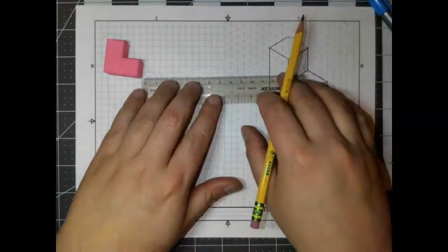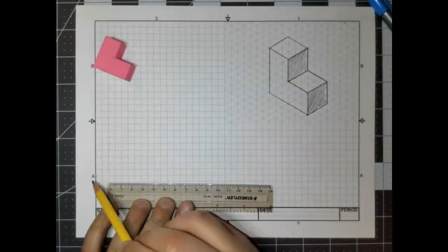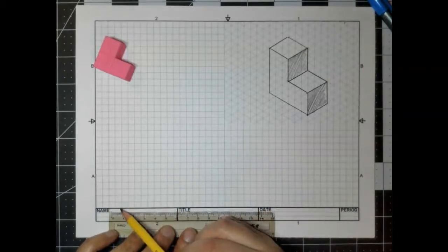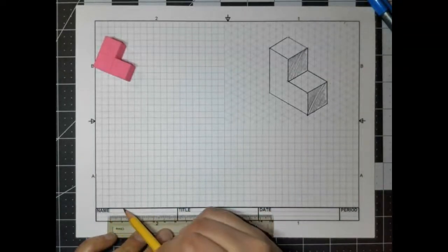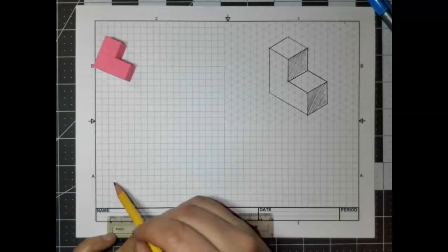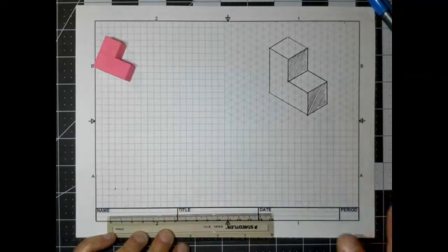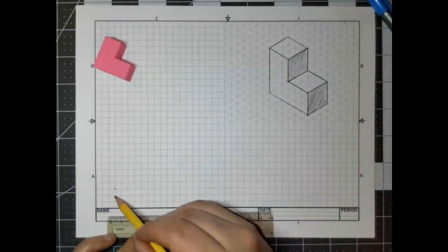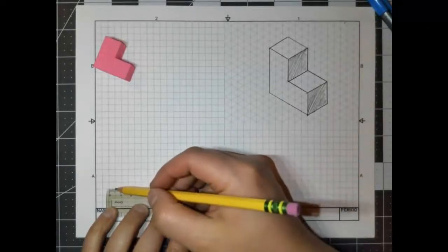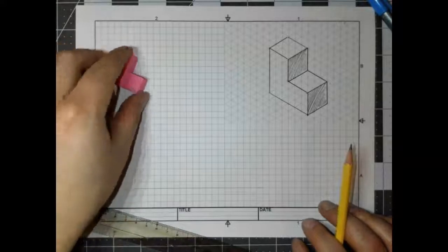So I need to start by drawing a very light line. Find the A and go a few blocks under the A. If you see the name part right here, there's this thick line. If you go up like 3 cubes and over 3, so that's 1, 2, 3, right here is a good starting point for most of your multi-view drawings. Sometimes you might need to go up 2, over 2. But what you need to draw is a construction line, and construction lines are drawn very light. A super light line, you can barely see it on the camera.